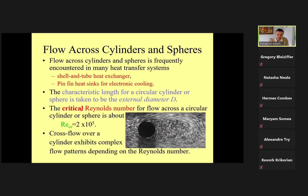And the critical Reynolds number, again, for the change from laminar to turbulent, is this one, 200,000. Therefore, keep in mind, even for external forced convection heat transfer, the Reynolds number is based on the diameter of the pipe, and the critical number now becomes 200,000 rather than 500,000. Therefore we have to look at here, and if you look at here, there is a very complex pattern that we can observe, depending on the Reynolds number that we have.